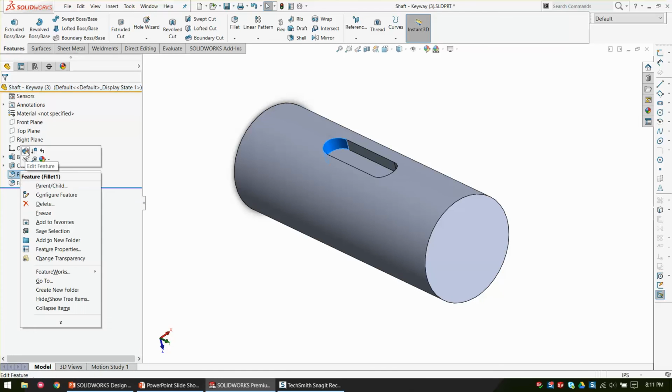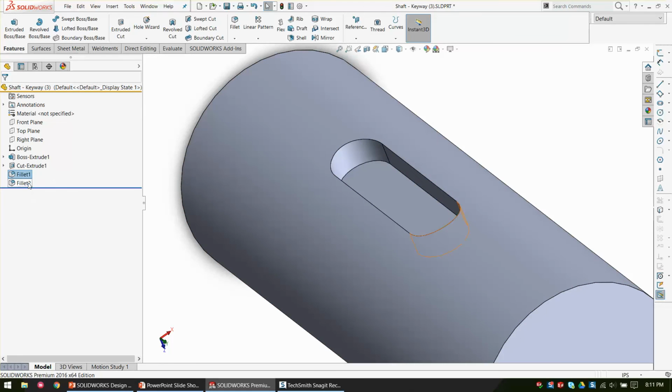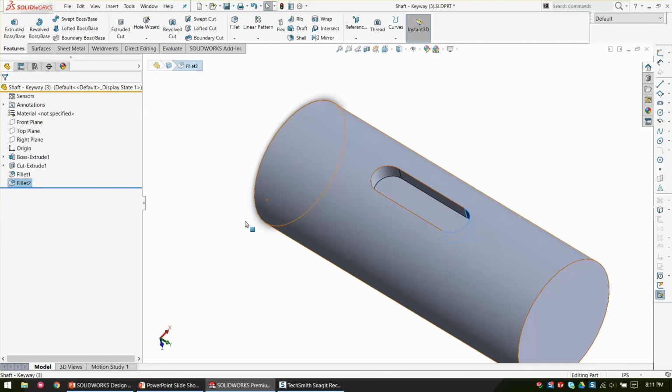And then here you would have two full radius fillets. The reason we do full radius fillets is because if this ever changes width, I don't have to update my fillets. Never want to update my fillets. My fillet is a full radius. If it goes from a 1/4 inch to a half inch, nobody cares. The problem is you just need two of them, which I'm not against features in the feature tree if they're good design intent logical features.